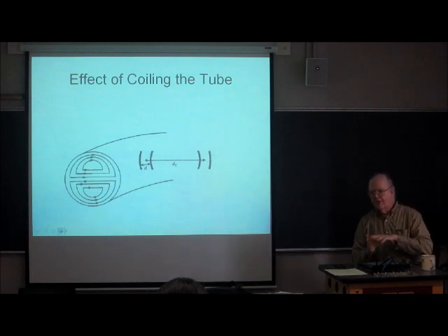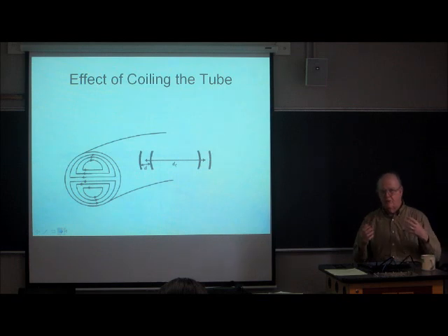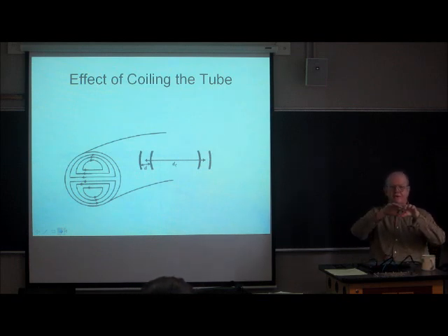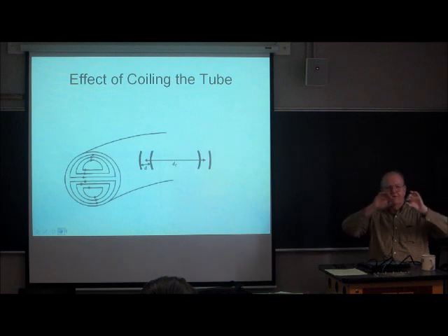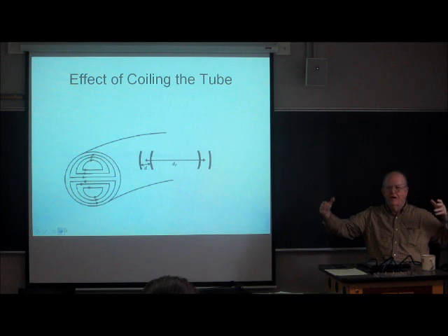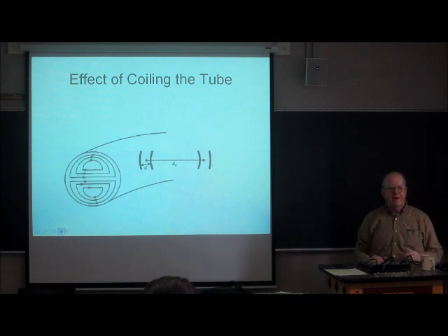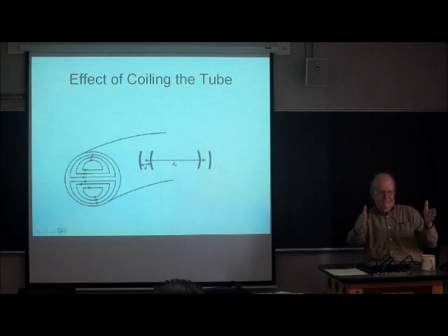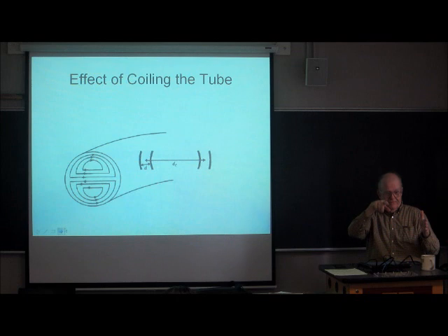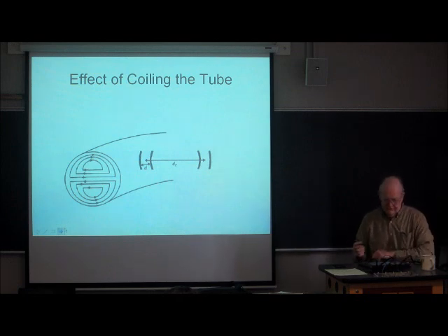There's one other issue that I didn't mention, but it's a real one, because more often than not, the tubing is not perfectly horizontal and it's not straight. You can't put 25 meters of GC capillary in an oven that's maybe about that big, unless you curve it. And if you curve it, you induce what's known as secondary flows.